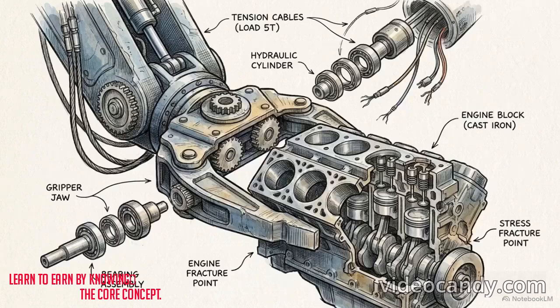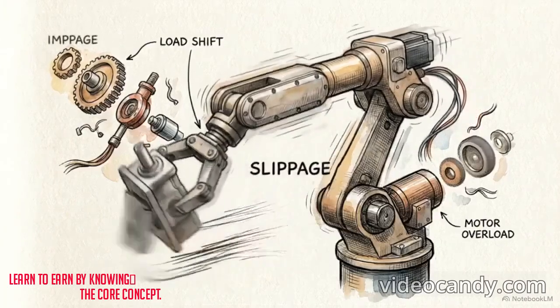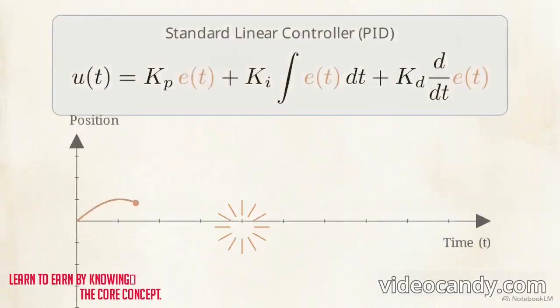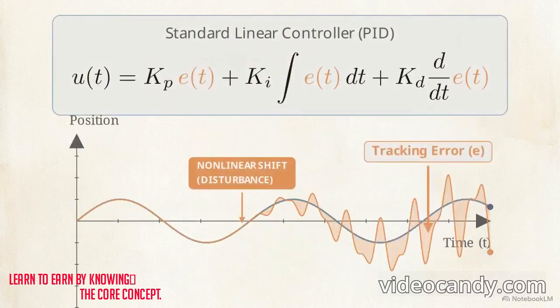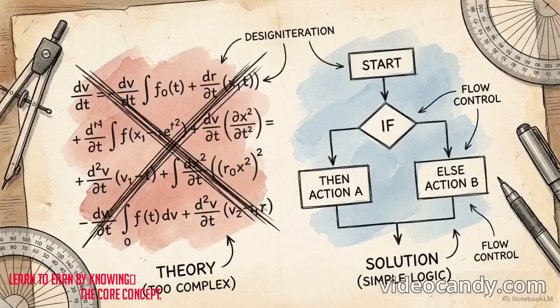When a sudden disturbance impacts a servo, the physical hardware must compensate immediately. If the controller is unequipped for the load change, the result is a visible loss of positional accuracy. Standard linear controllers, such as a basic PID, respond to these changes through a continuous calculation. However, they often lack the response speed needed for nonlinear shifts, leading to significant tracking errors. Maintaining precision under these conditions requires nonlinear strategies, specifically fuzzy logic and variable structure control.